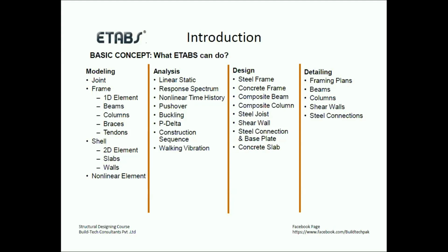So keeping in mind, you will go for the design check. In the first stage, you have taken some trial sections. If some of the members are failing, like ETABS will show you it is failing in shear, maybe it is failing in flexure or something, you need to increase the sizes of those members' trial sections.